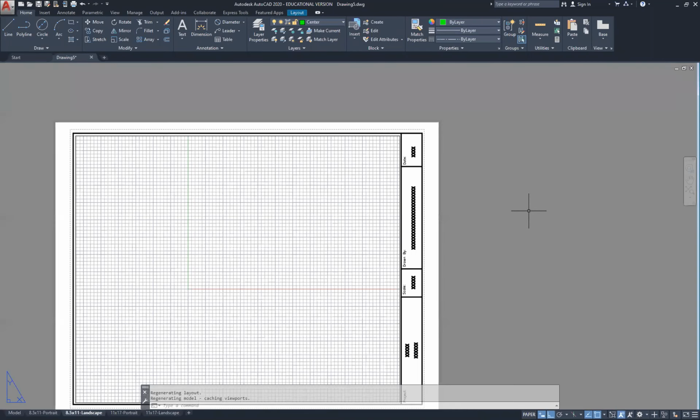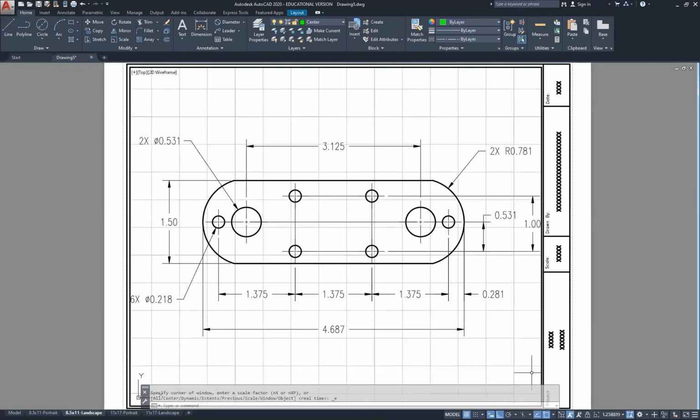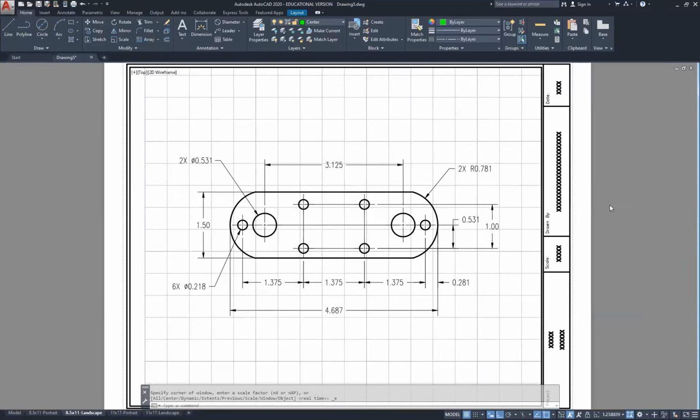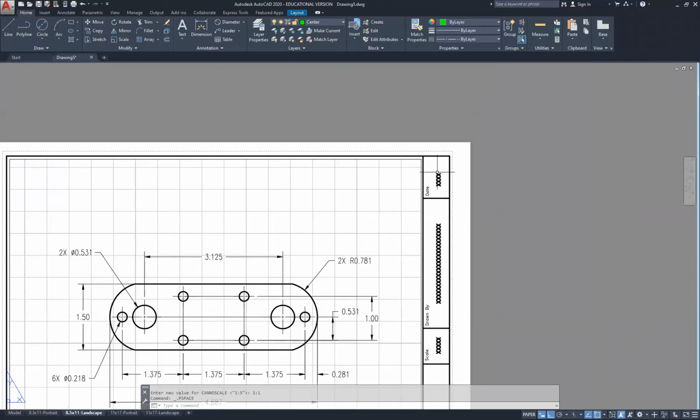That brings me into the viewport. From here, I'm going to hit my center scroll button twice, zooming to the extents of the drawing. From here, I'm going to change my scale to 1:1. Now the drawing is scaled correctly. On the outside gray area, I'm going to select with the left click twice to get out of the viewport. This is now the part where you're going to put in all your notes for the project, the scale, drawn by, and the date.